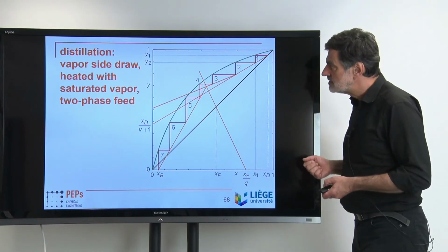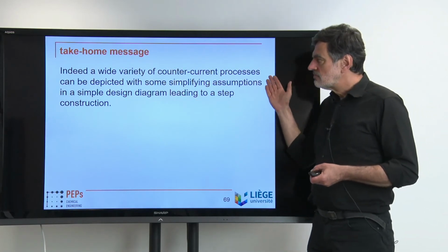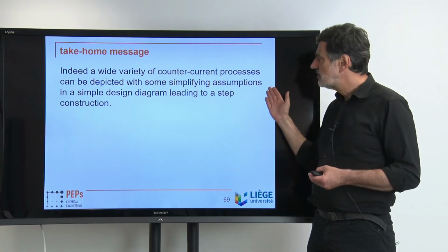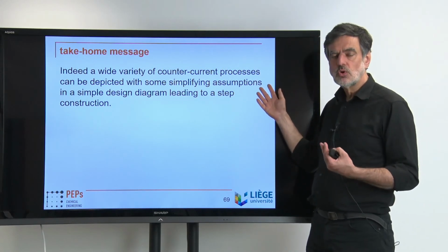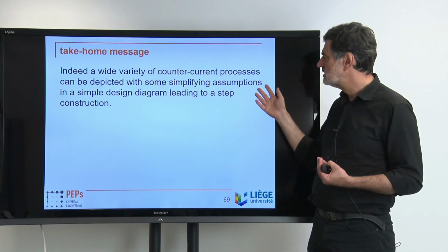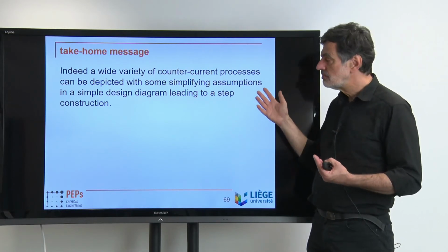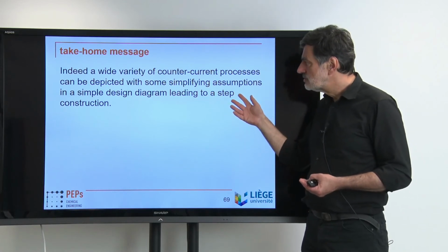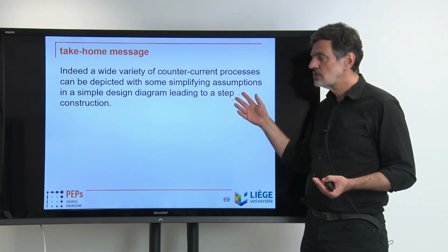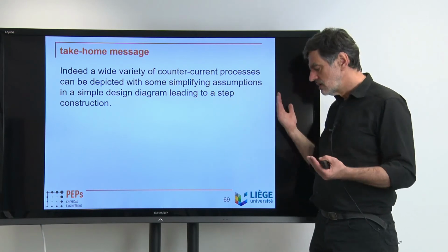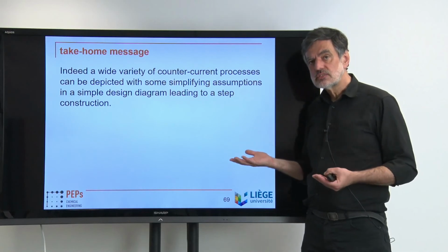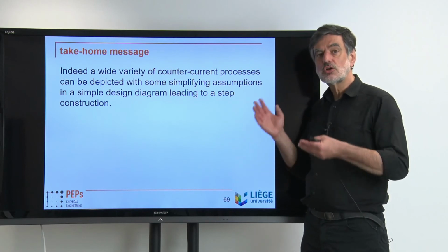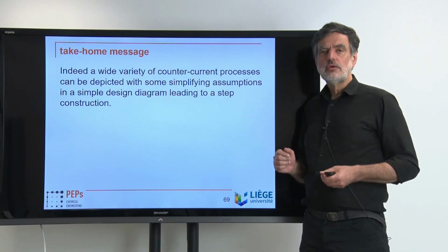And with that, we can realize that overall, we have a wide variety of countercurrent processes that can be depicted with some simplifying assumptions, of which we typically find one set that is fulfilled, so that we can apply it with some accuracy at least in a simple design diagram leading to a step construction. That step construction is then often called the McCabe-Thiele diagram, in the YX diagram that represents the corresponding separation process, and that allows us to determine the number of theoretical stages graphically.